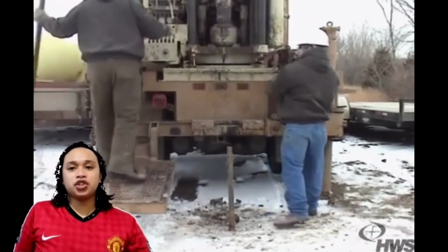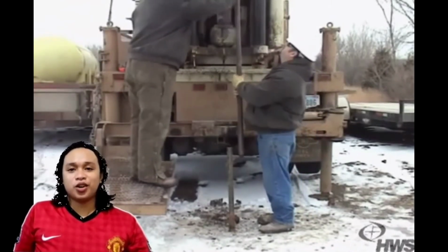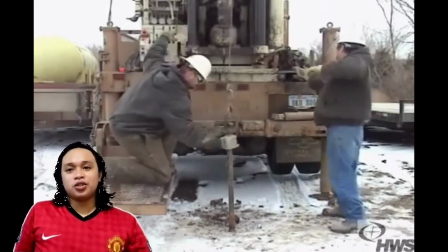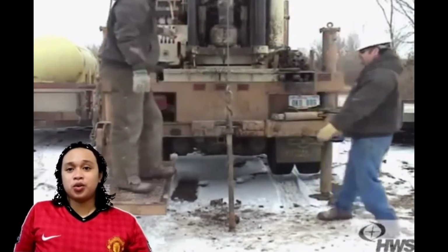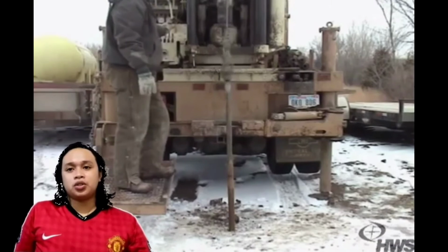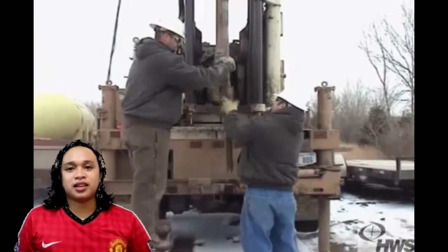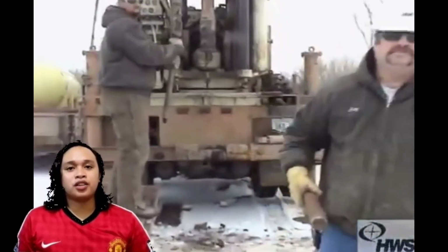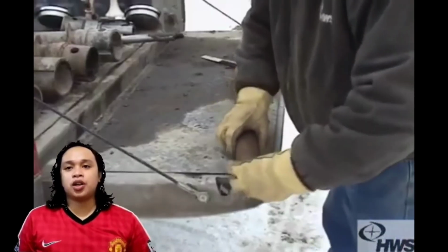Further, it should be ensured that the three legs of the tripod are firmly supported. The soil below the legs should not be loose, and they should not be supported on a sloping rock surface or on a small boulder which may tilt during testing. Advance the borehole at the test location using the auger. To start with, advance the borehole to a depth of 0.5 meters and clear the loose soil from the borehole.